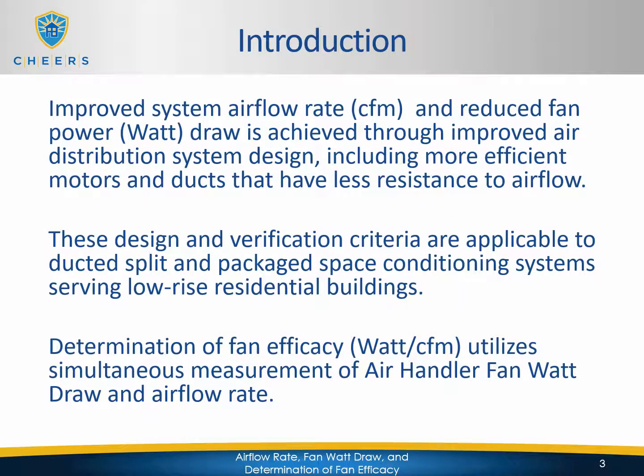Improved system airflow rates, or CFMs, and reduced fan power and watt draw is achieved through improved air distribution system design, including more efficient motors and ducts that have less resistance to airflow. These designs and verification criteria are applicable to ducted, split, and packaged space conditioning systems serving low-rise residential buildings. Determination of fan efficacy, watts per CFM, utilizes simultaneous measurement of air handler fan watt draw and airflow rate. So basically, the purpose of this test is to make sure that the systems are not using any more energy than they have to per CFM being produced by the actual system.